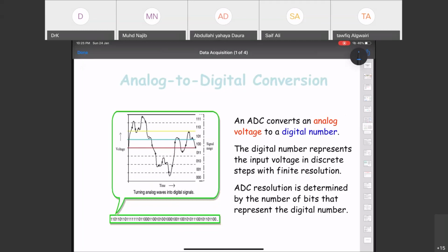Now it is very much defined by the number of samples that you receive in a second. We also look at different sampling frequencies, and what kind of effects you can observe in your signal. And you also know that the higher the sampling frequency, the more information you will have, which will improve the precision. All right. But at the same time, it means more storage, because you have more data per second.